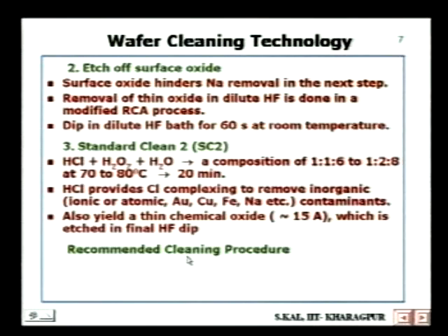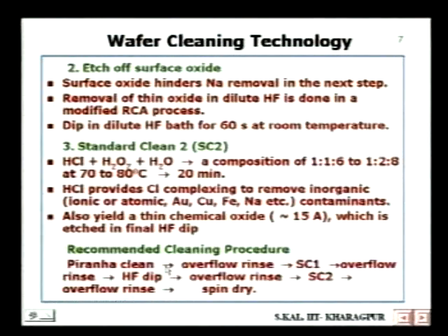The recommended cleaning procedure of silicon wafers is as follows. First we go for Piranha clean. Piranha clean is also known as the Caro's acid cleaning. What is Caro's acid? It is a mixture of H2SO4 and H2O2 in the ratio of 1:1, that means 1 part concentrated sulfuric acid and 1 part hydrogen peroxide.